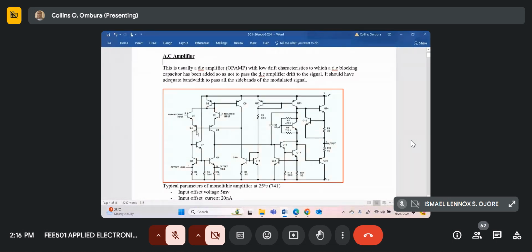And then, of course, the other thing we've got to ensure is that all the resistances used inside the circuits, all resistances generate noise. Remember, the noise generated by a resistance, V noise RMS, is root 4kTBR. That's the thermal noise generated by the resistance.